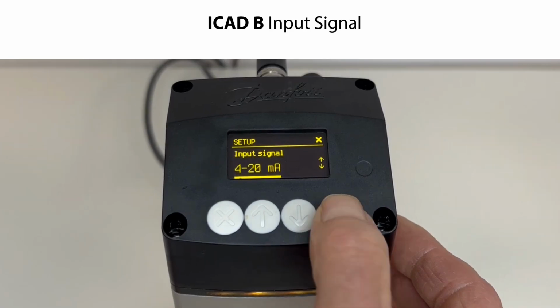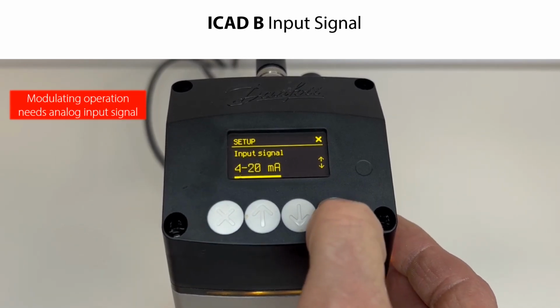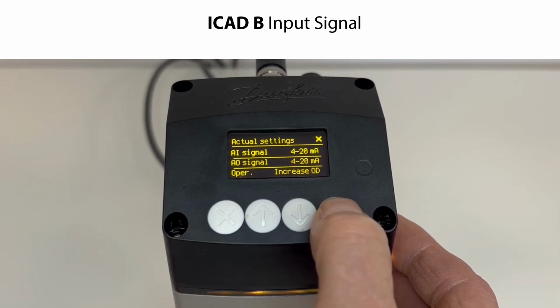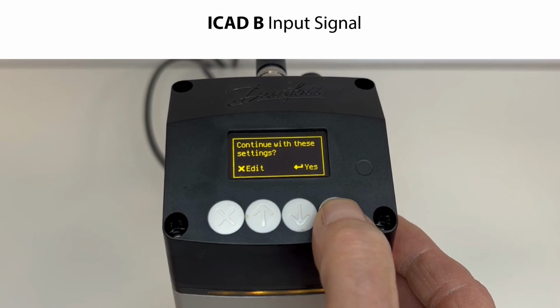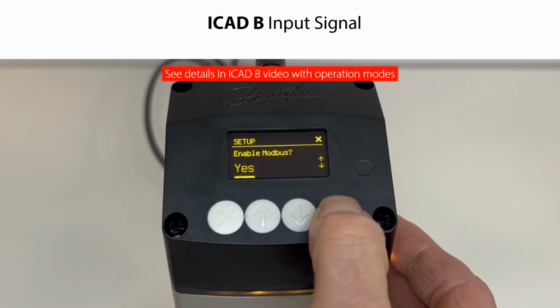Since we have selected modulating operation, we should now select an analog input signal. As seen, the default value is 4 to 20 mA, and in this example we keep this value. Therefore, press Enter several times to confirm this. Please see more details about operation modes and input signals in a separate ICAD B setup and configuration video.